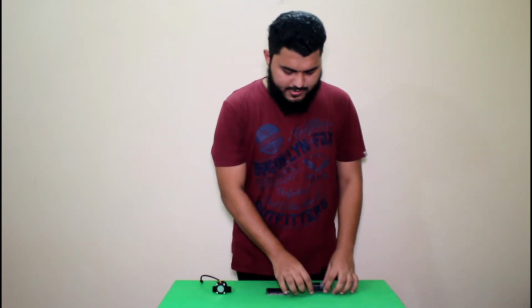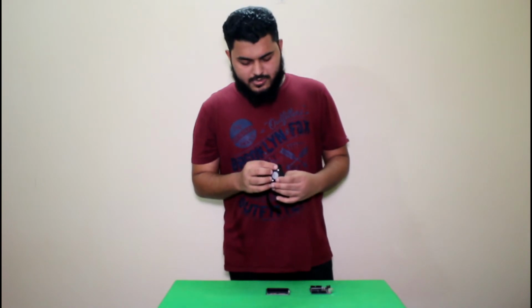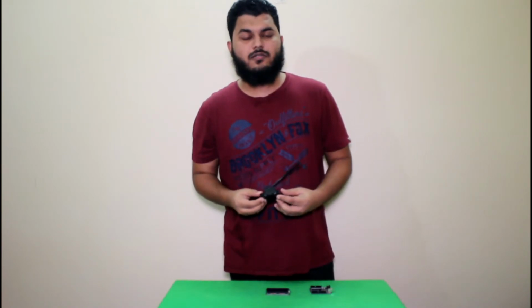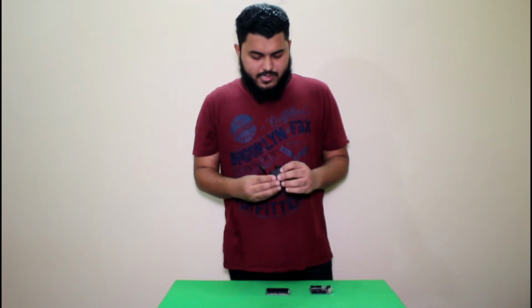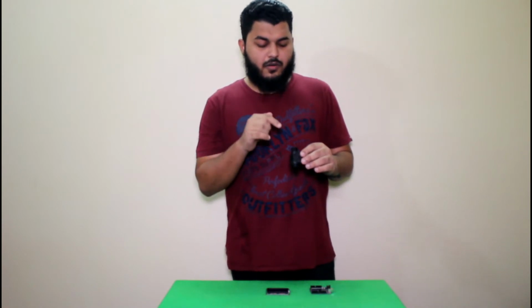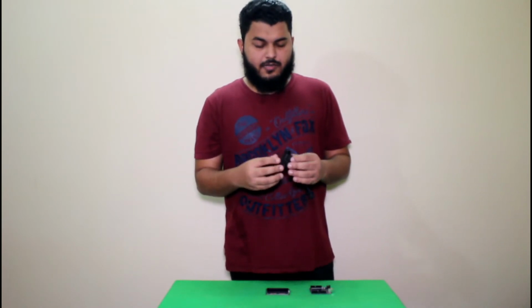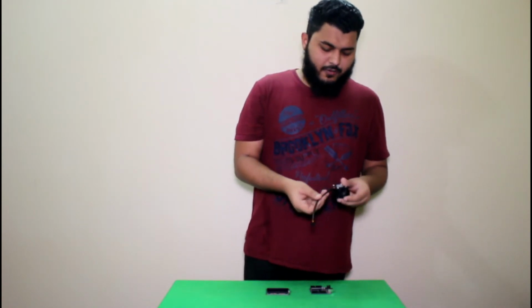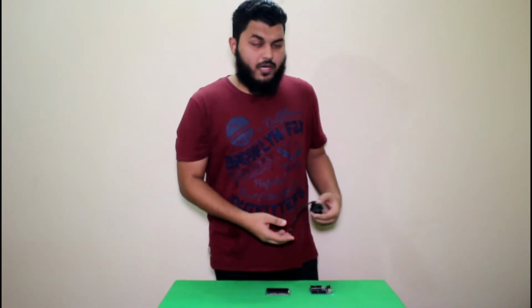The next component is the water flow sensor. This is a widely used water flow sensor. We can see it in coffee machines or other devices. It mostly contains one rotor inside, and the outside body is plastic. Whenever the rotor inside spins, a value is taken, and whenever the speed rises, the value of the flow sensor also rises. There are 3 wires. We can connect it with our microcontroller, and it will give the value in the process.